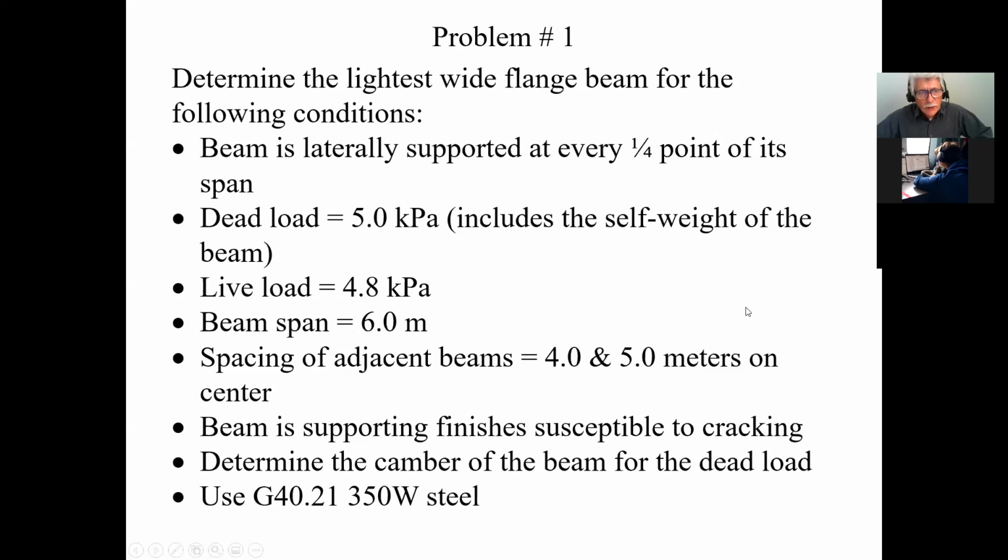Nice load. Now here, when I say the spacing of adjacent beams are 4 meters and 5 meters on center, what I want you to understand is that this is the beam we're trying to design here, and of course it's supported somehow in plan view. Here's our beam, and this just represents columns that I'm putting in.